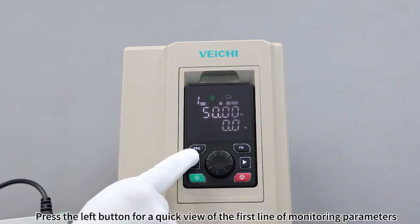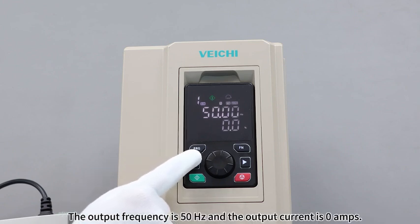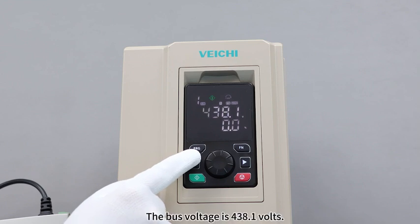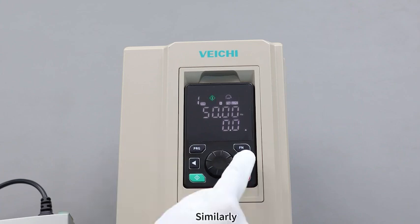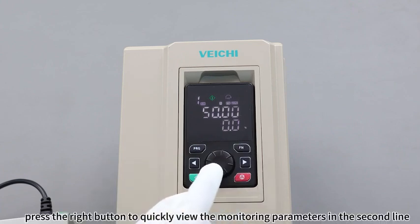Press the left button for a quick view of the first line of monitoring parameters. The output frequency is 50 Hz and the output current is 0 amps. The bus voltage is 438.1 volts. Switch to the given frequency. Similarly, press the right button to quickly view the monitoring parameters in the second line.